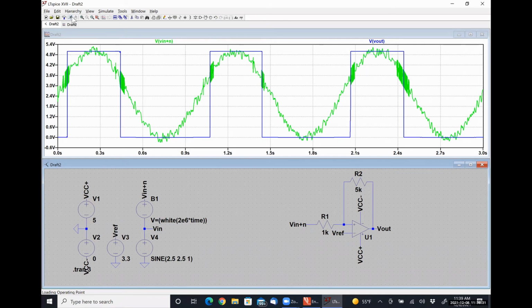So we can play with the gain in here and see what happens, right? So right now, we're just illustrating the point that we get the nice, even output without all the crazy fluctuations and all that kind of stuff. So this handled some of the noise for us, but we don't have a simple single comparison anymore, right? We no longer have when Vn is greater than V reference, it's high; when Vn is less than V reference, it's low. Now we have these latching mechanisms kind of built in, which is absolutely a useful thing.